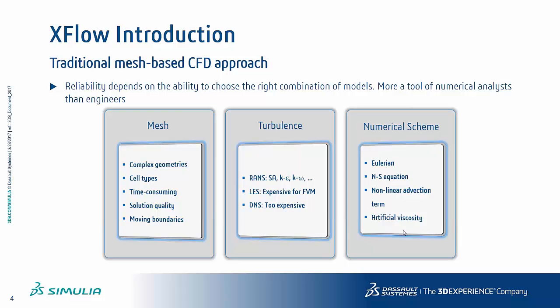Your code usually needs also to add some artificial viscosity so that it converges without any numerical issues, and this type of artificial viscosity also damps the physics, especially for unsteady flows, especially for acoustics, where on the contrary you try not to damp things, but you need very high scheme orders in order to maintain all the pressure and acoustic fluctuations in your flow.